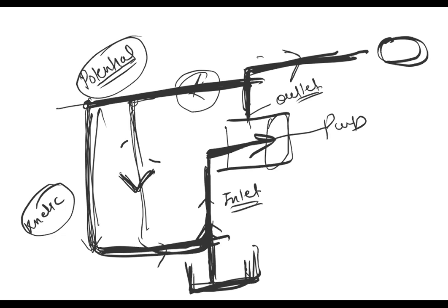That is why the efficiency of a jet pump is very low. If you have a jet pump, it will take so much time as compared with a submersible pump to fill the same amount of tank. Why? Because it is taking only 50% of water outside the system. 50% is always in the recirculation zone. It is approximately 50%, I am saying; it will vary according to the pump.